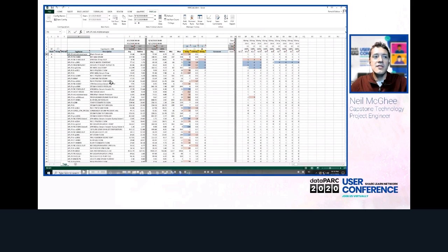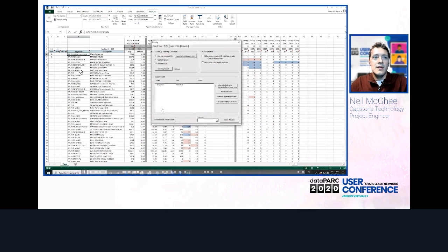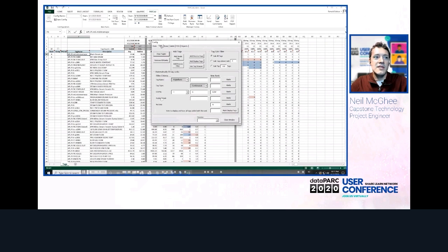We can continue to rank these tags manually, but in the tag configuration tab, we have some bulk sorting options that we can use. First, we want to assign all tags a default rank. We will go with B here. Tags that have had very little variation within the baseline period are less likely to be important since they are well controlled, but we may not want to delete them entirely because any changes these tags do have might be significant, so we can just lower them to rank C.